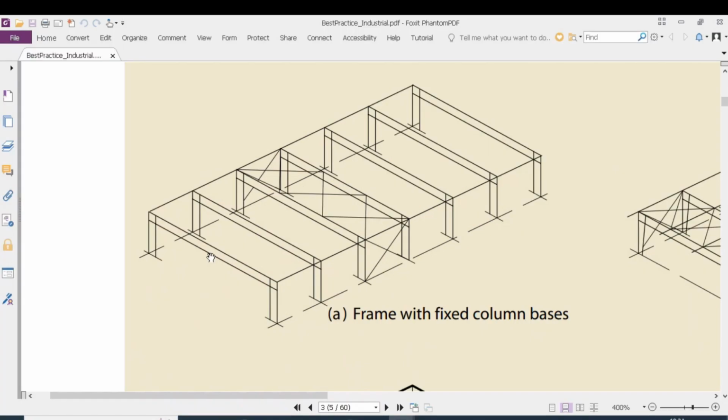In order to cover a single space with portal frames, we can arrange the portal frames in series behind each other at some distance center to center. After that, all the portal frames can be connected by horizontal members shown in this figure. As we can see, in the plane of the frame, the structure is stable.